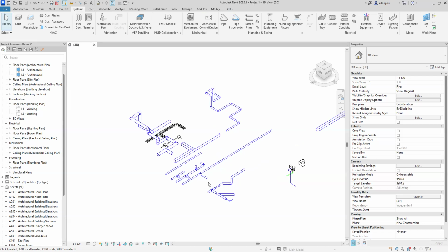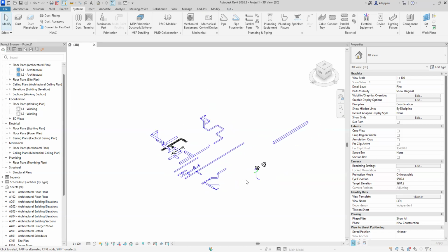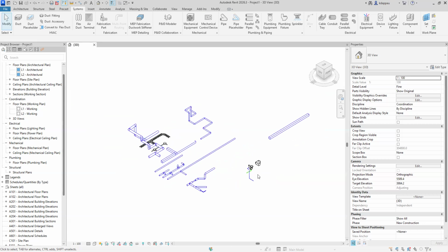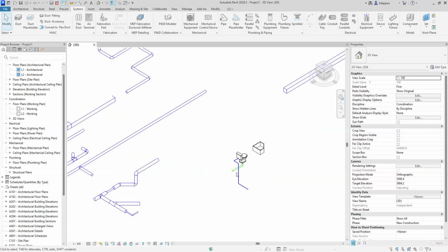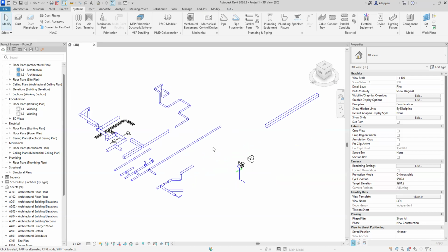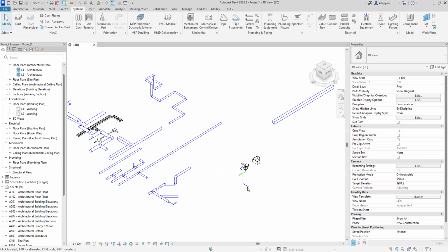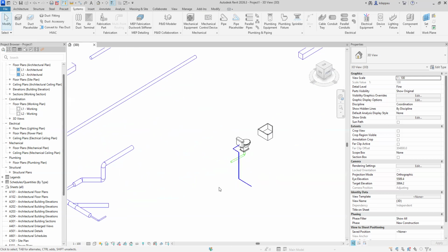But when you put the WC and we linked a pipe from the waste end and a pipe from the supply end, the waste end changed to green and the supply end is blue. So I'm assuming when you are drawing a waste pipe, that is what is going to come. You can edit the color to any color you want.